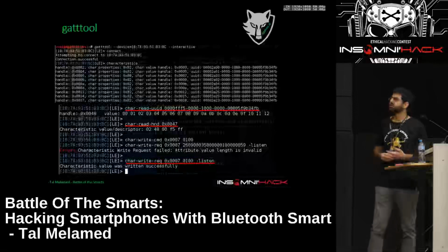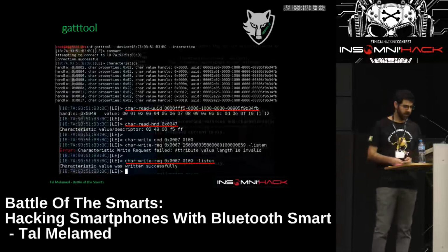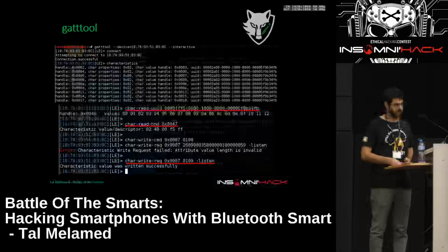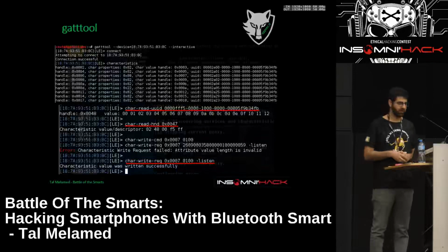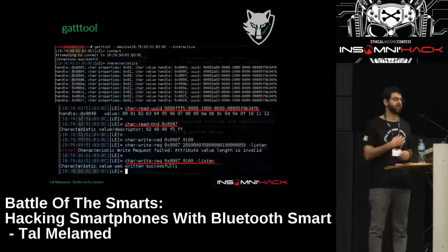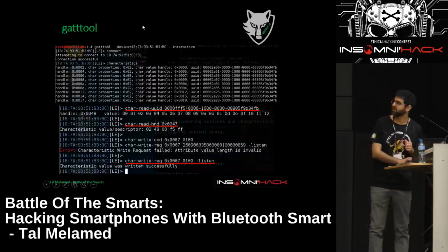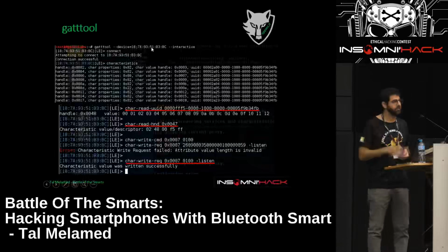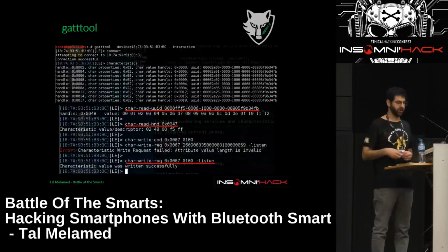Okay, there is another tool. Wow, you can't really see. It's called gatttool, GATT from the Generic Attribute profile. And it actually lets you communicate with the device from the command line. So with gatttool, you set the device MAC address. You can't really see that, but later the presentation will be uploaded and you can see.